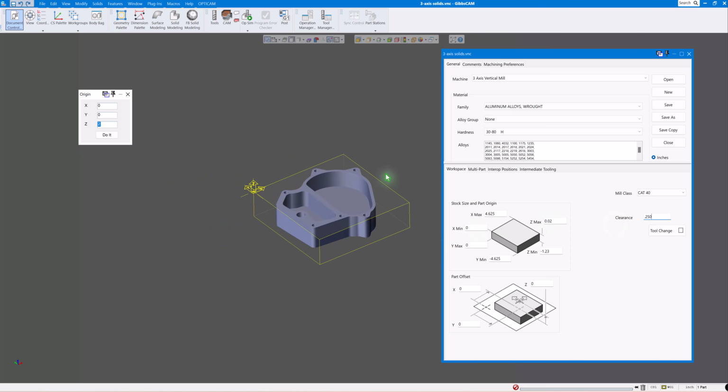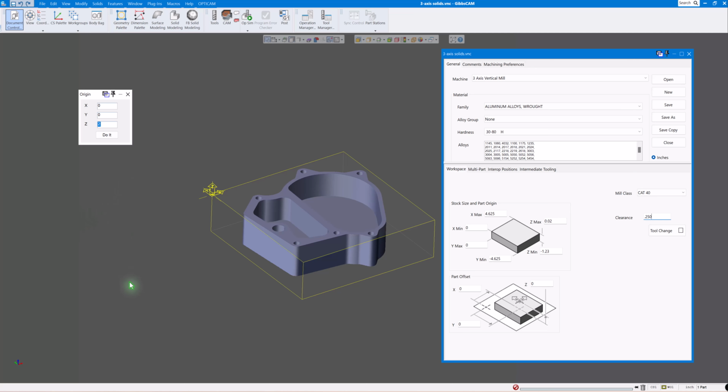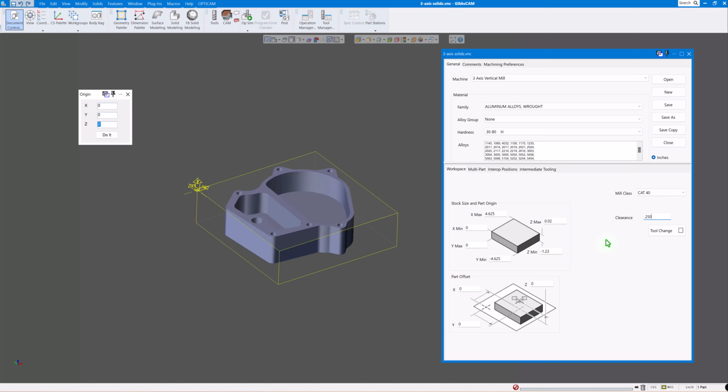Okay, you might not see it on the rendering. When you render it in Gibbs, if your tool starts outside the part, you may not catch that tool going way deep and then back up. If it was on the part, of course, you'd see it when it rapids down and in, but be careful actually making your part, so make sure your clearance is good there.